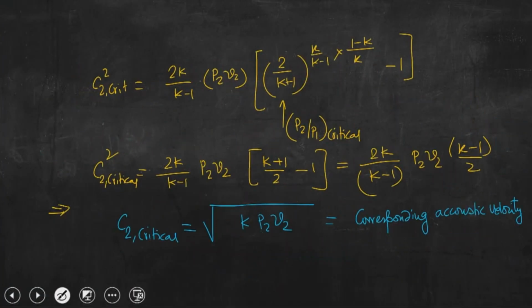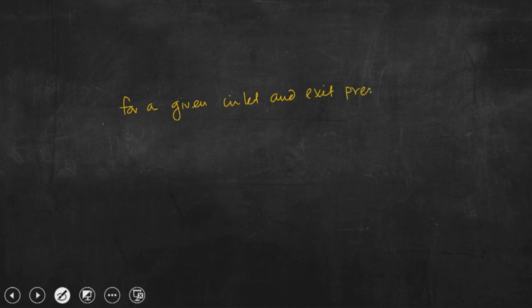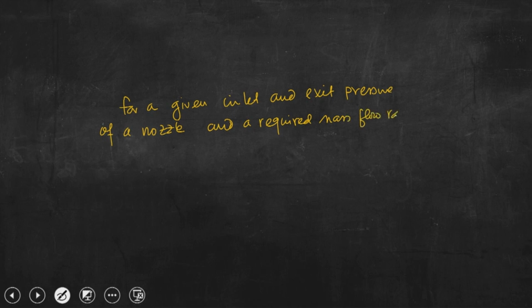Let me write here: for a given inlet and exit pressure of a nozzle and a required mass flow rate, the nozzle designer has to evaluate the critical pressure first.